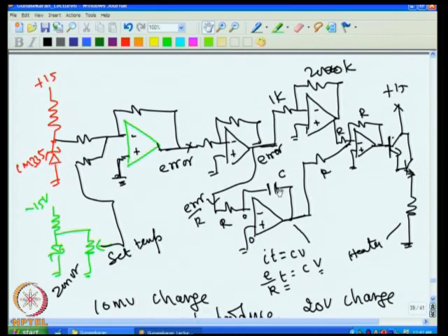This I leave it to you to think for some time till my next class comes, because in the next class I will explain how you do this. You can work out and see mentally how to convert this electronic time constant from the temperature time constant that we are expecting, because we can also show you from the control theory that the time constant of this integrator should be equal to the system time constant if you don't want the system to oscillate.